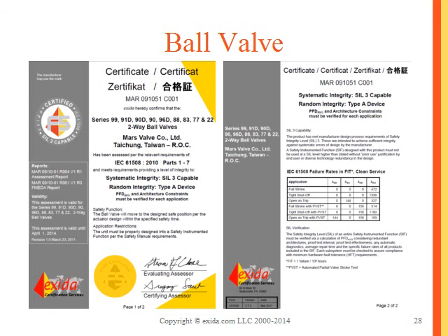A ball valve here, and this again is an example of an older certificate. The reports are on the front here, the failure rates are in the back. You will see a full stroke application where only on-off is basically being used, an application where tight shut-off is required. Doesn't mean that the valve cannot do tight shut-off in the first case, full stroke. It just simply means the tight shut-off is not required as part of your safety function. You only need to achieve a full stroke to achieve the safe state. In the second example here, you will require tight shut-off to go to the safe state.